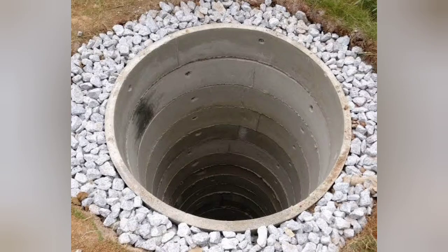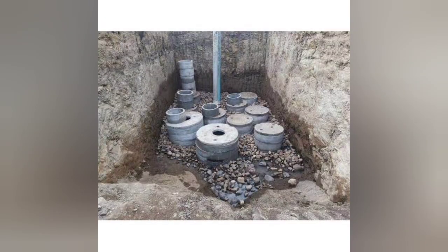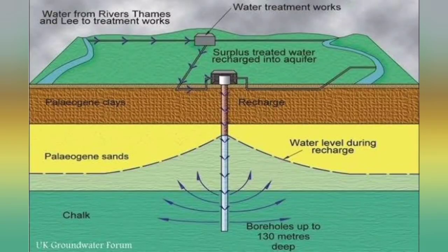The artificial recharge of groundwater is normally taken up in a few areas. The areas are like where groundwater levels are declining on a regular basis, areas where a substantial amount of aquifer has already been desaturated, areas where availability of groundwater is inadequate in lean months, and areas where salinity ingress is taking place. So in the first part of the planning, we need to identify the area. Then we need to have some scientific inputs. The scientific inputs are like